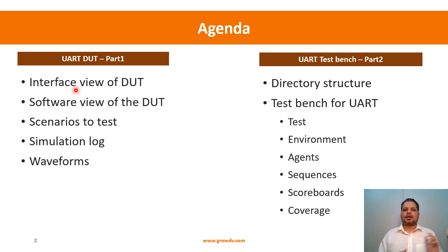So for the UART DUT, we will look at it from an interface view of the DUT, that is, what are its signals and how do we connect it, because we need to connect this DUT and pass these signals to our test bench. Second, we'll look into a software view of this DUT, because we need to build the UVM RAL model for it, and then we need to build the sequences which program the DUT to transmit something or to read the data our UART DUT has received.